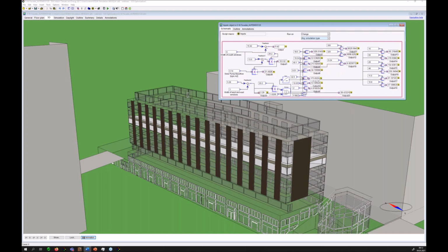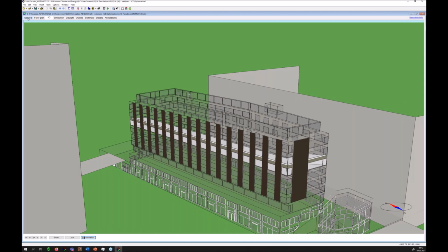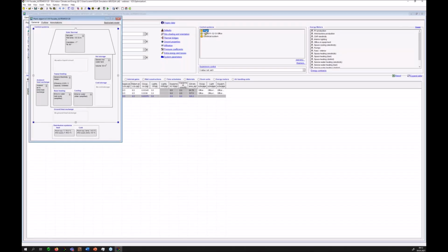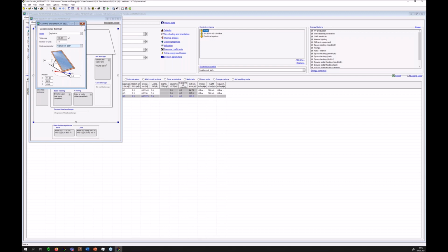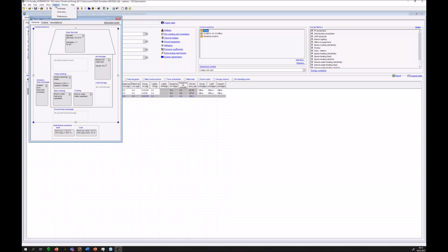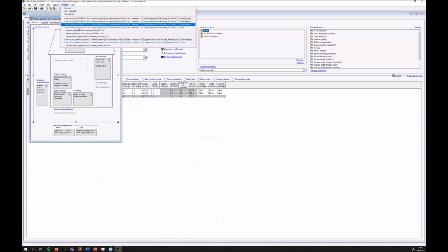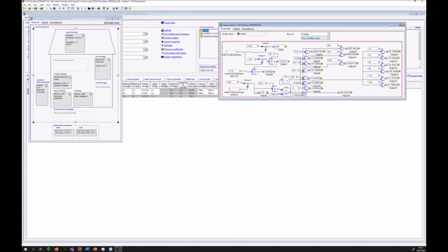And for the south facade, we also defined the window width as a parameter. So here it's the same thing. I vary this parameter, and you see that the windows and collectors are adapted simultaneously. Together with the size of the collector field, we also vary the size of the tank. This is now a direct parameter here, so I can vary this tank size here. And I'll go back to my inputs.